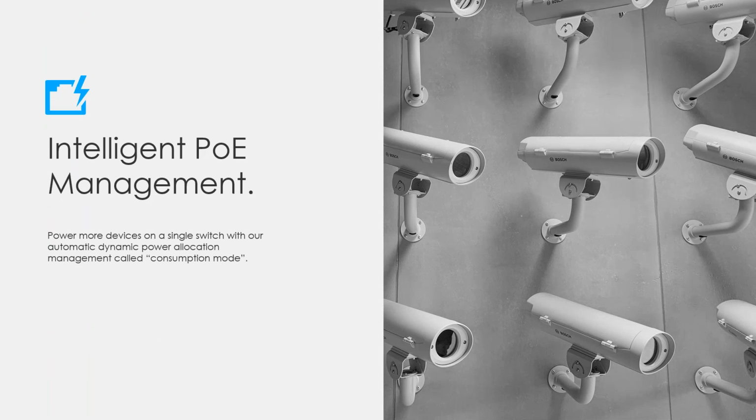Okay, so the ways we can get around this: we support consumption mode and we support classification mode. In classification mode, we give the classified amount of power required, even though the device might not actually use all of that power. As standard, we use something called consumption mode, in which we only reserve the amount of power for the device that it actually consumes, so no more than that. So we can more efficiently make use of our PoE budget.